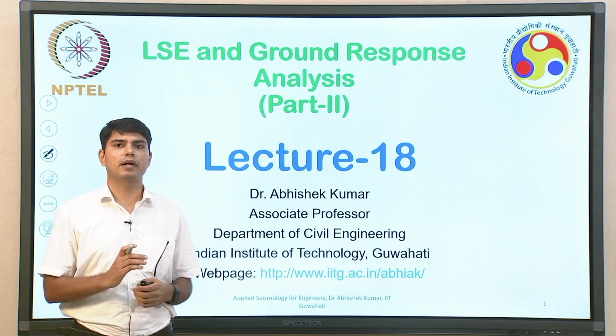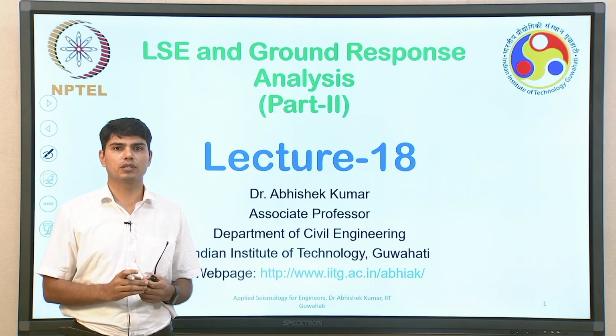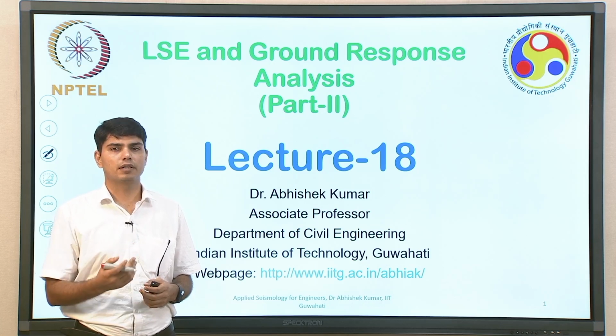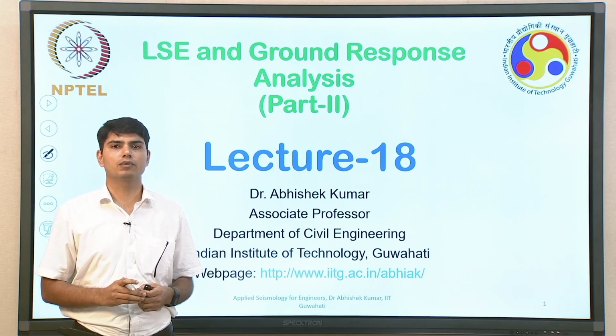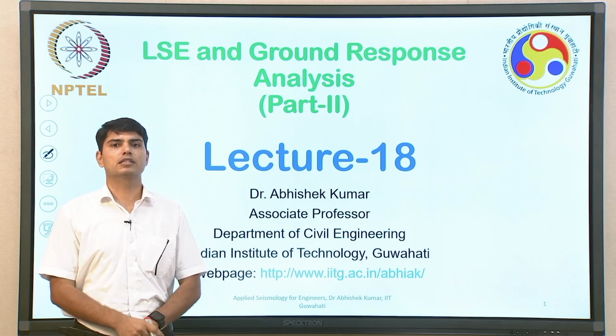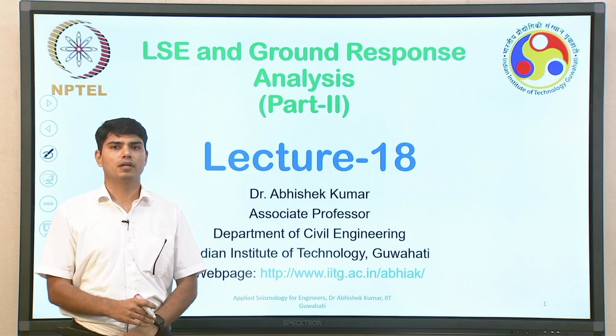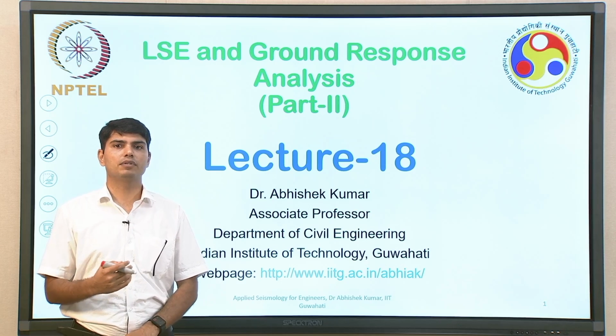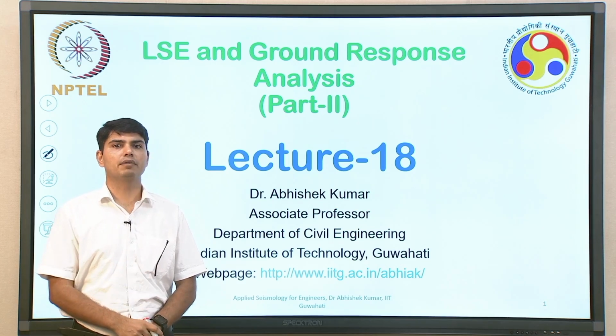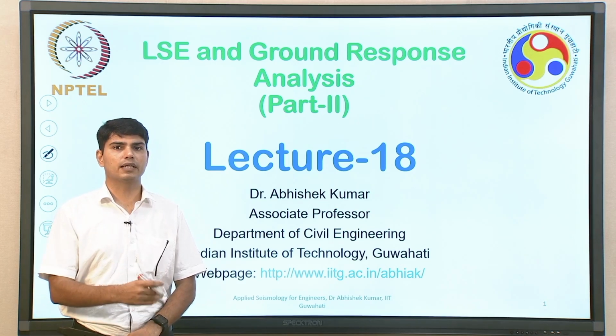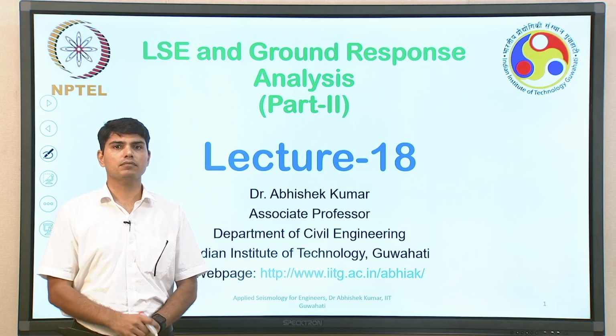In such a case, the particle will undergo to and fro motion in the direction of wave propagation. Then we determined the governing equation of motion for the primary wave. Followed by that, we discussed what if the secondary wave, that is the wave which follows the primary wave, or reaches second at the recording station, is propagating through a particular medium.